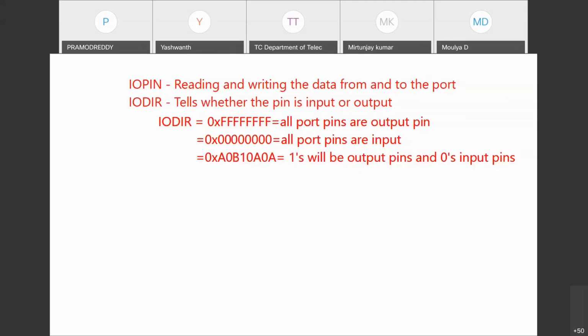If I assign the value 1 and shift it by 3 bits, I am choosing P0.3. Counting P0.0, P0.1, P0.2, shifting 3 times, the meaning is P0.3 will have the value 1.